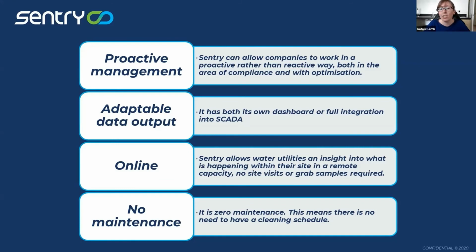And then the final advantage is that it's online and no maintenance. When I say zero maintenance, I spoke earlier about that ammonia probe and how you have to take it out and clean it. This isn't the case with this probe because it's designed for those microorganisms to grow on it. For instance, we've got a SENTRY unit over at United Utilities that's actually been in place for 2 years now, no cleaning whatsoever.